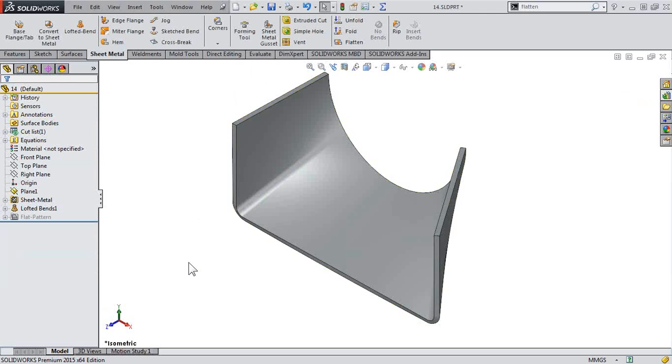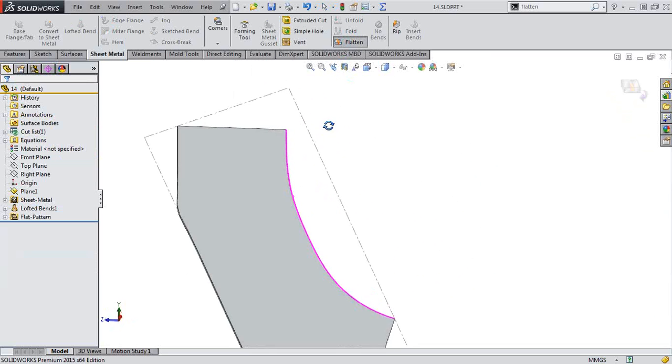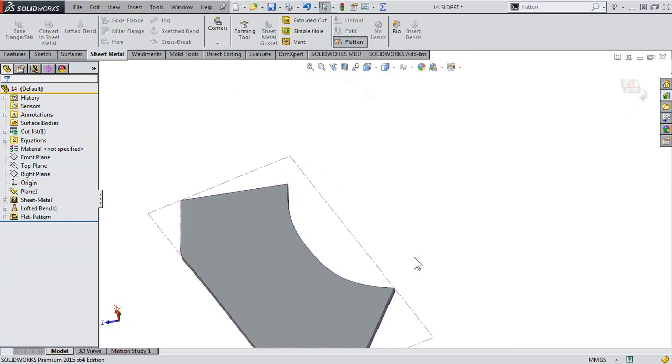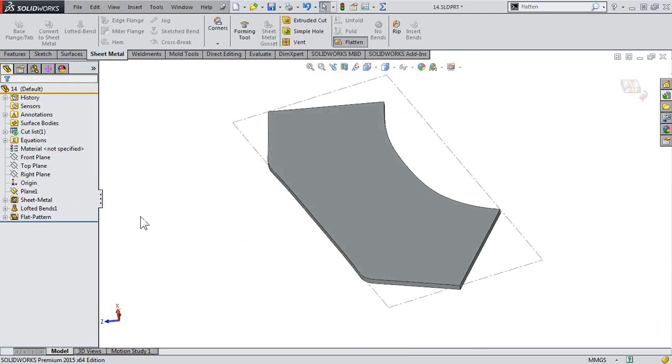But here with that formed option, we can generate that sheet metal part, we can generate the flat pattern, but guess what? What do we not have here? Bend lines. Of course, in this case, this was because the number of segments in my sketches were not equal.